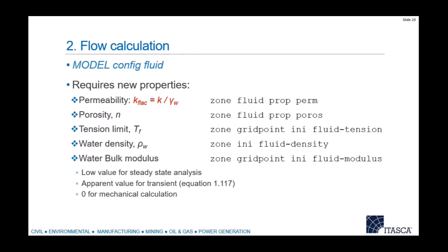So let's say what we know then is we know that on the way up slope, this is the pore pressure distribution, and way down slope, this is the pore pressure distribution. So we want to calculate what that curve looks like rather than assign it, okay?